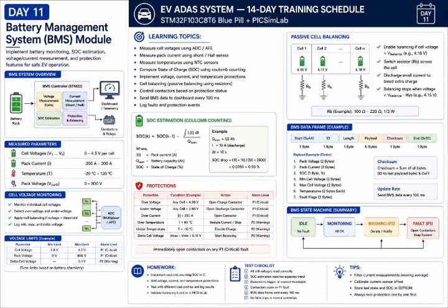And coming to day 11, I developed a Python based dashboard. It displays the vehicle speed, battery SOC, power consumption, motor temperature, torque, and driving mode in real time for the electric vehicle. UART packets from STM32 were decoded and visualized using Python libraries, creating an interactive EV dashboard, that is, electric vehicle dashboard.